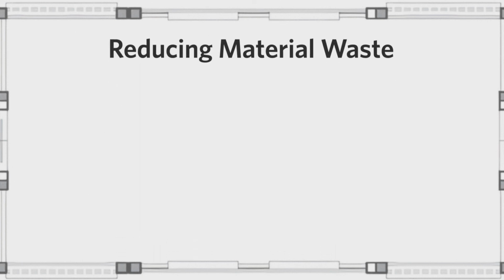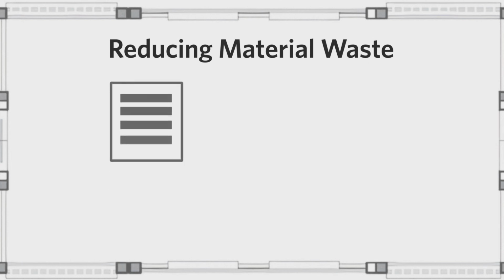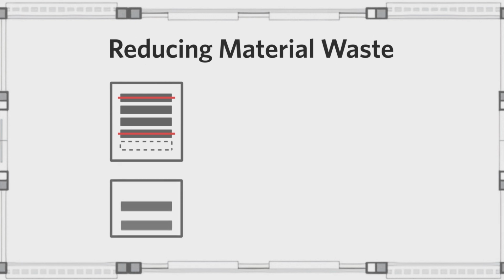Second, reducing material waste. The old method creates a large amount of waste for two main reasons. First, its starting point is the original takeoff, which is susceptible to rounding errors, changes in plans, missing markups, or estimator errors. And second, it relies on the installers on site to be extremely efficient in their use of stock length material, which is not often possible. This results in 10 to 20% of the total material wasted.